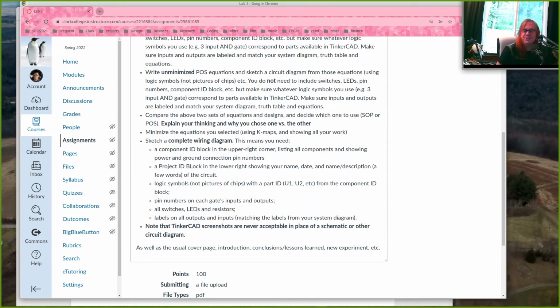And what do you put in your test? "I tested it and it worked." Not sufficient. Because how is somebody else going to reproduce what you did? So how are you going to test this? Well, you've got 3 switches, you've got 8 combinations. And they represent different situations. So put your switches in a configuration which means there are no cars present. And what should your lights do? Well, it's up to you. Maybe one light will be green, maybe they'll all be red. Did you observe that? Well, make a note of it.